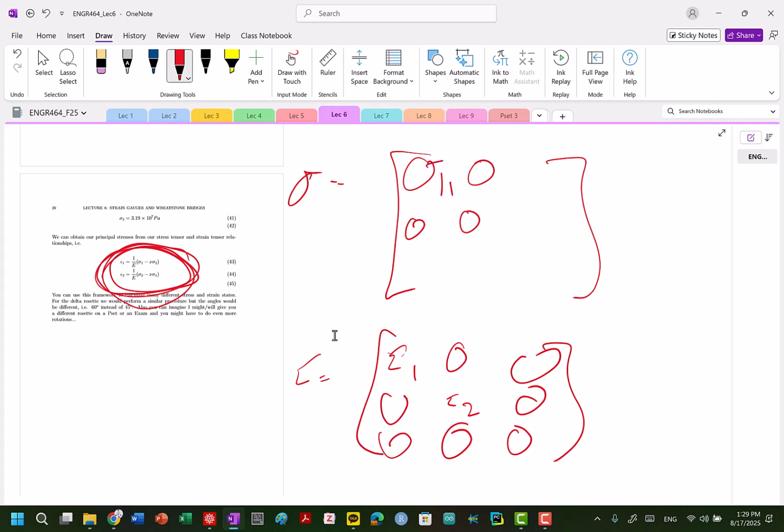So your sigma 1 will exist, sigma 2 will exist. So you can calculate that out. And I think you can assume that that's an interesting question. I don't think we can necessarily, I mean, if we're assuming that we're in plane stress, there could be a strain in the 3-3 here. Actually, not if we're using that, because we have to be in plane stress, excuse me. That must be 0. So, excellent.